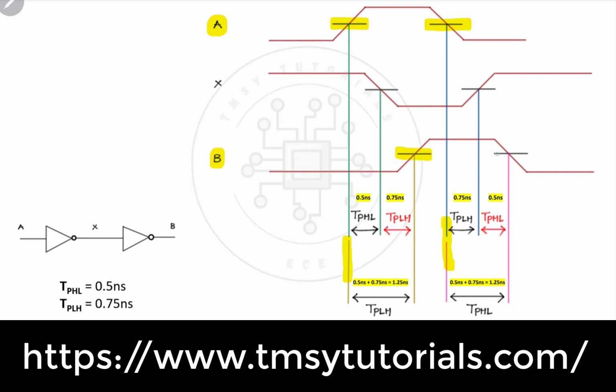At the 50% point of B, take vertical lines, and we need to write either TPHL or TPLH depending upon the transition of B. If you observe here, B is changing from low to high, so it will be TPLH. So I wrote it as TPLH. Similarly at this point, output B is changing from high to low, so it is TPHL.